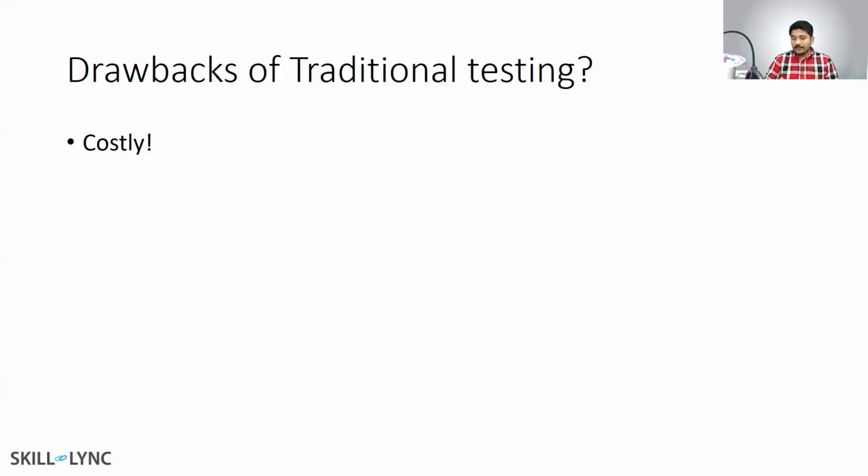Shivananda, I'm kind of answering your question as well. Take 5 to 6 experimental configurations and run your CFD simulation for them. If the answers deviate, what is the error? If it is within 5%, it's okay. Then see if you're getting the same trend as your experimental data. If you are, you can use the same mesh strategy and solution algorithm strategy for your case. Shivananda and Deepak, does that answer your question?